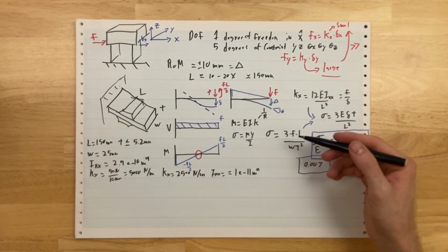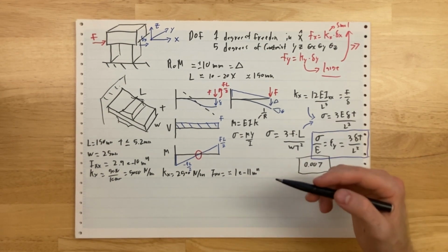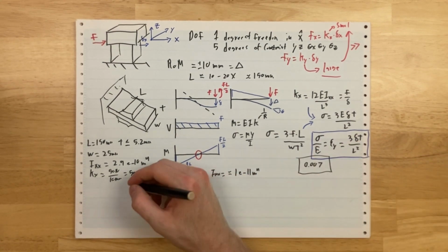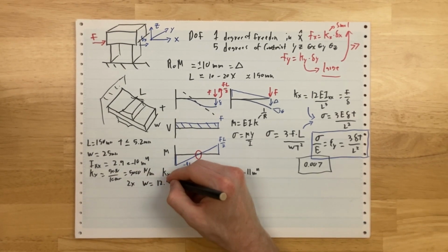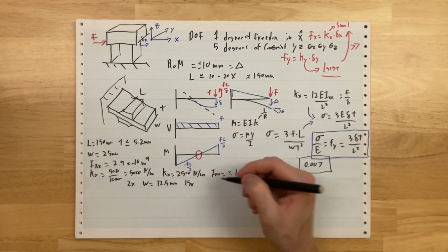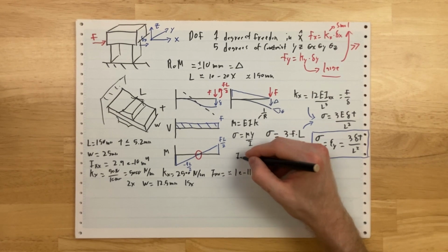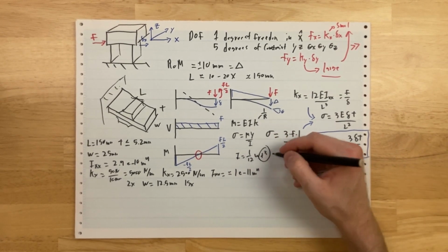This is a common problem in flexures where you choose one thing and then you find out you're off by almost an order of magnitude on some other variable that you care about. So what can we do here? If I need 30x, I'm going to take 2x out of the width and knock the width down to 12.5 millimeters. But then I need to take 15x out of the thickness. In I for a beam, 1/12 W T cubed, the thickness is cubed.